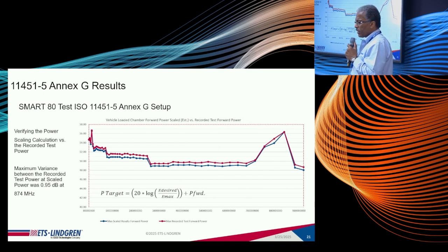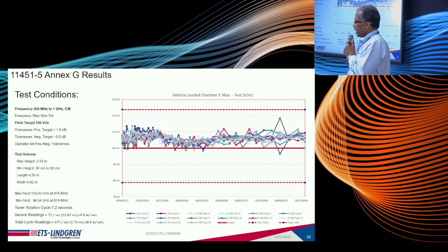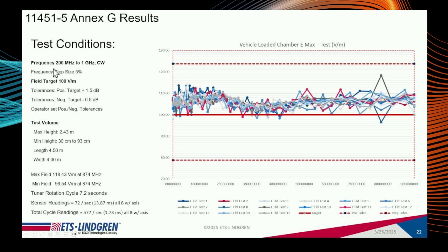And here you can see that the variation in the average is fairly close to the calculated value based on those 8 probe measurements. And if you factor that into an actual immunity measurement, you can see in this example, where your target field strength is 100 volts per meter, your variation in field is fairly tight. And in a reverb environment, this is a pretty good result, and really as good as it